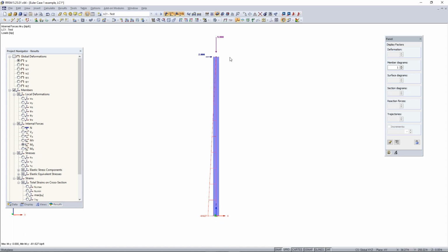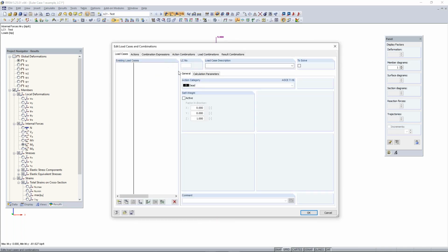And this is a result of the increased deformation, which leads to the applied axial load having an increased moment arm. And so you can see how taking into consideration second order effects can really increase or lead to higher results within your structure. So keep this in mind, that you will get two different results when switching between first and second order analysis. And like I said, load cases are always run by default as a first order analysis.